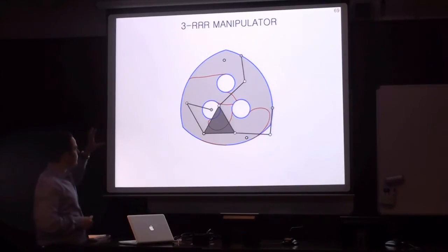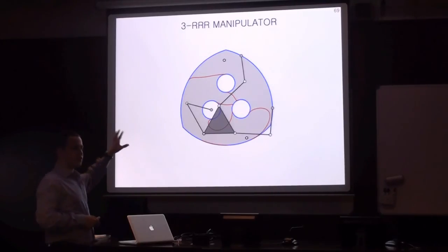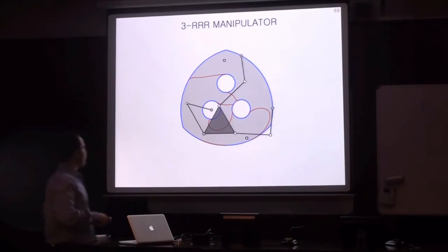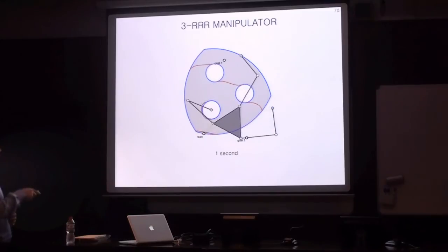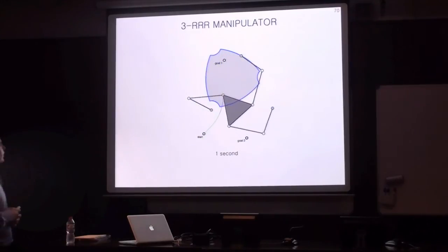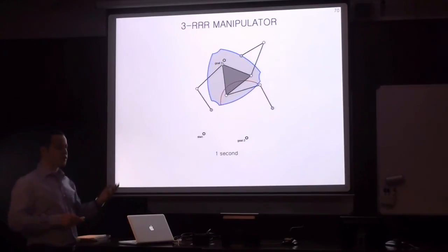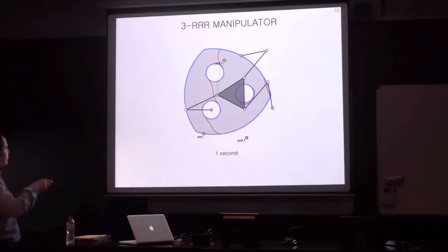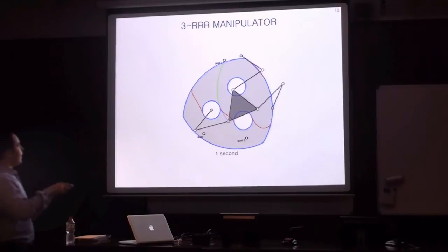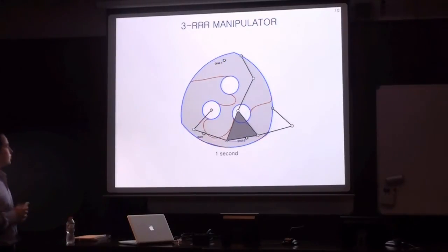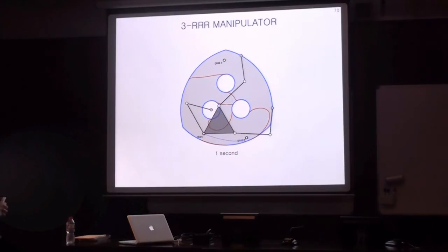And this is because at each moment we are showing the constant orientation slice of the singularity sets that corresponds to the orientation of the platform. So this is the path that we obtained. You will see that this point never crosses a singularity, and that the algorithm by itself is able to take advantage of the change of working mode. For example, now this leg will change working mode, and this leg will also change working mode now. And these paths were computed in just 1 second.